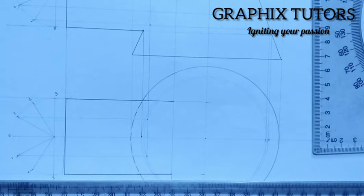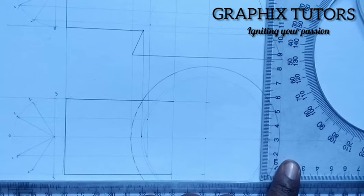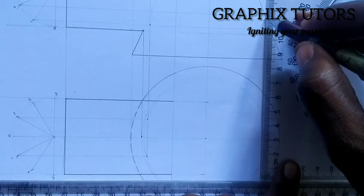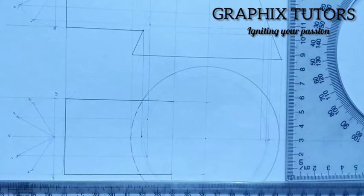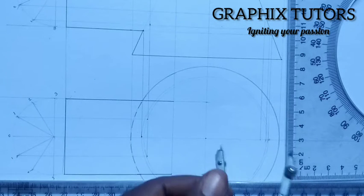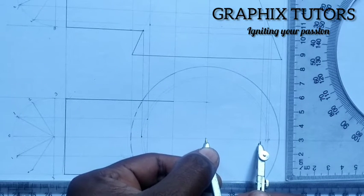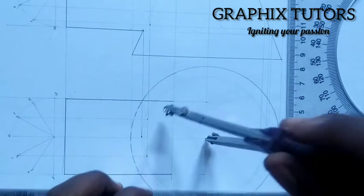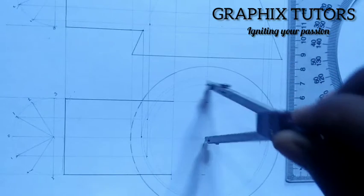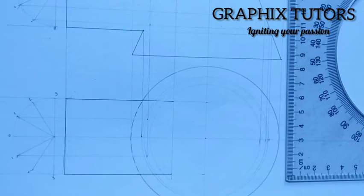Now the next thing, I'll go to 2. This is 2, which is this point here. I'll draw it down to touch here. That'll be my point 2. I'll take my compass, take it to 2. And I'm going to draw my circle. Right?